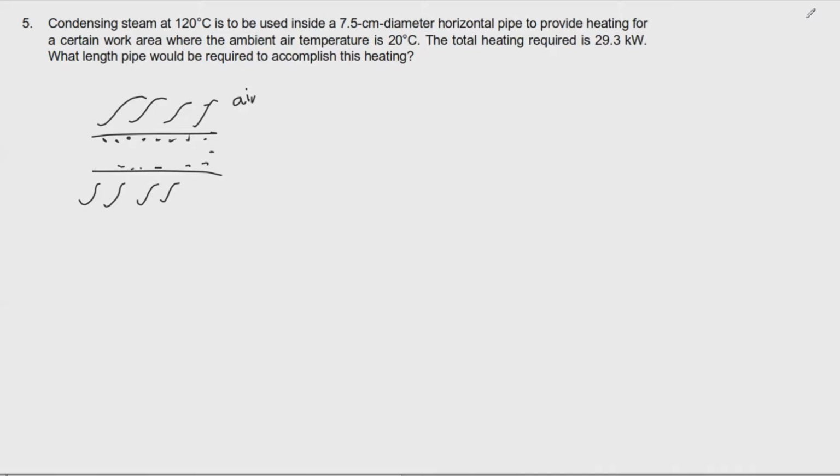And particularly, the role of this steam is that it is used to maintain the temperature on the surface, not in a way that this steam would condense because the temperature on the inside is lower. It's not something like that. It's the opposite. So in this case, we're not considering something like a condensation or change of phase, but this is still the normal natural convection on the external of the material. So still we'll be using the same equation as what we did before. But before that, we need to check on the condition first.